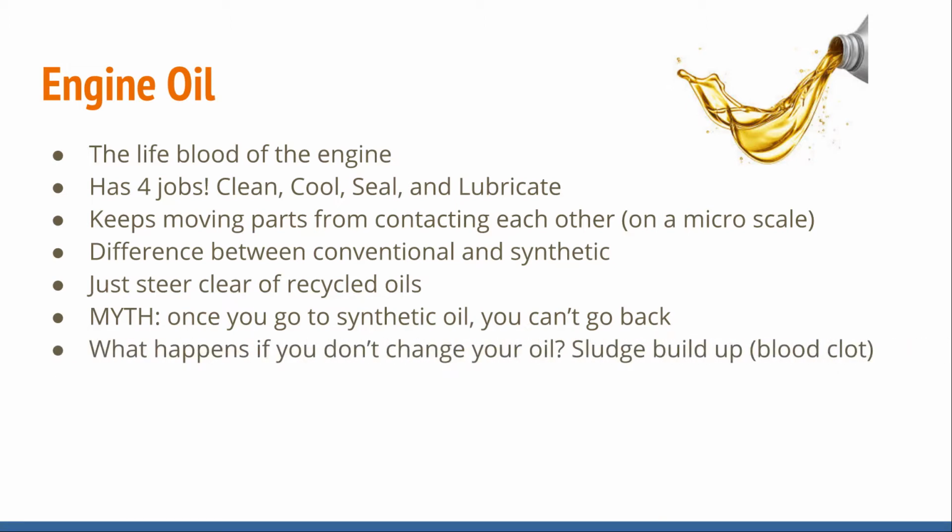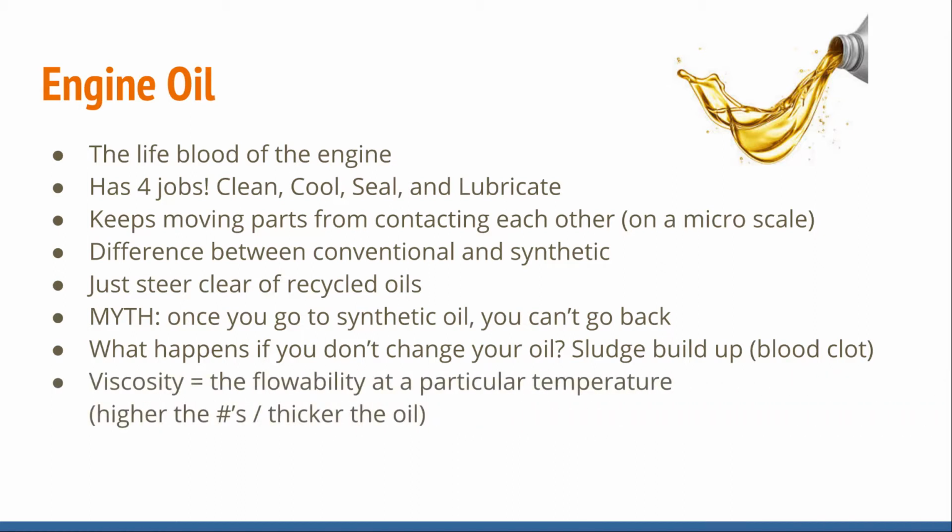Okay, we talked about this. What happens if you don't change your oil? Sludge buildup can also be thought of as a blood clot. There are tiny orifices that go through your engine. So all that sludge, just like a blood clot, builds up over time until the oil doesn't come through there like it should. And then that's when we end up with oil starvation and parts that wear out. And it does happen. You'll open up engines and see there's nothing but sludge inside there. And a lot of times that's the cause of the failure.